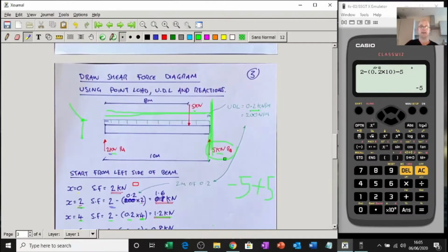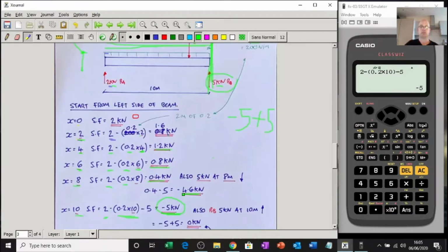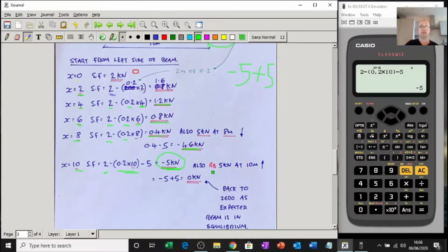And then this thing here kicks in, which is the +5. B is +5. That's how we know we're correct. So now I'm going to get the +5 coming back up, which will bring us back to 0. Starts off at 0, ends in 0. That is how I know I'm correct with my reactions. If you're miles off there, then you know your reactions are incorrect.